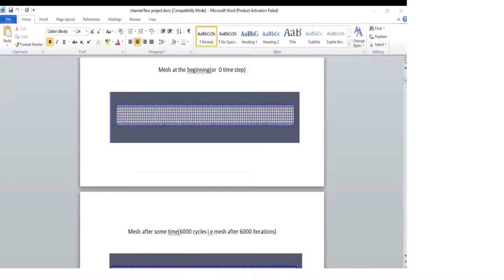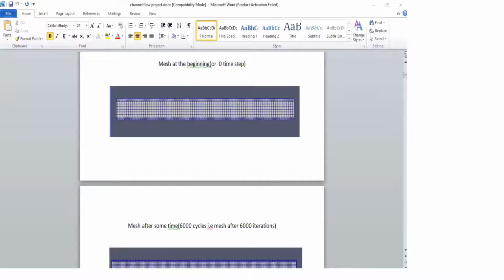So if I open my Converge Studio, and close this, I'll open the fixed embedding, and here it will ask for which boundary you want. I have not defined the top and bottom boundaries yet, so let me do that. Then only it will make sense. In the boundary, let me create top and bottom, and top and bottom is just no slip. Front I can keep as a wall also, and I will keep it as symmetry.